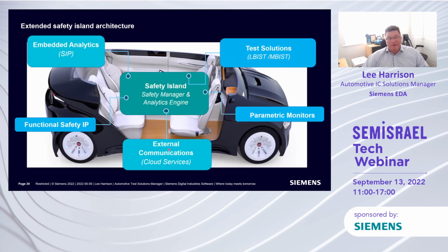If we extend this concept still further, what we can do is combine, using this safety island concept, not only the test technology, but also the embedded analytics technology, any functional safety IP, and any parametric monitors that you have in your device.